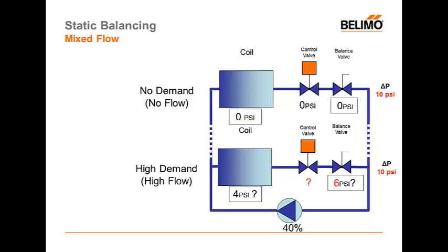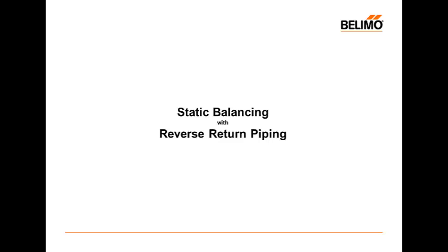Balancing valves can create problems of overflowing all of our coils, but you can see another scenario here where we've caused a massive underflow that has starved this zone. Now, if we had utilized a pressure independent valve, or even a flow limiting valve for that matter, in this case we would not have seen this particular type of problem.